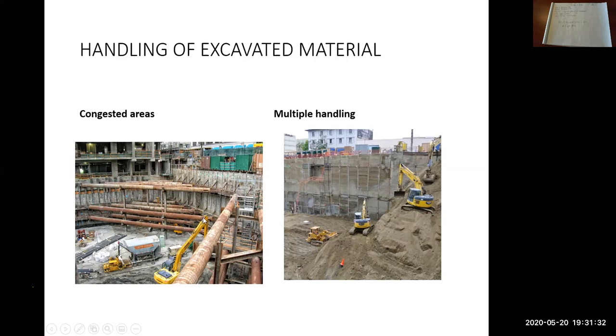Again, this entire system would be engineered, so it would be designed by an engineer. Likely it would be you, the contractor, providing that design work. The owner would not typically provide that design. So here is the stair tower that I talked about before. That's a scaffolding type system where it's erected starting on the bottom and they stack it all together. So it's a staircase all the way up, and then you can get out here on the side.